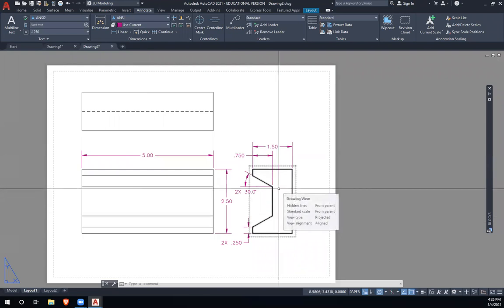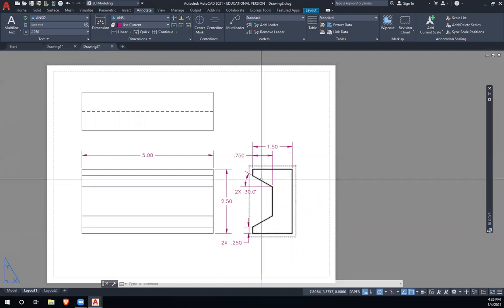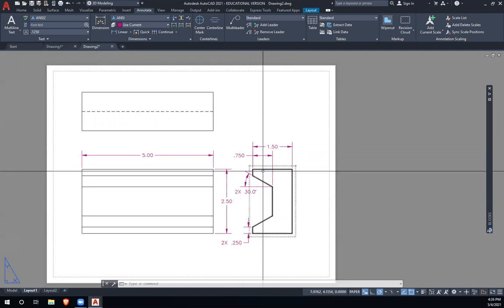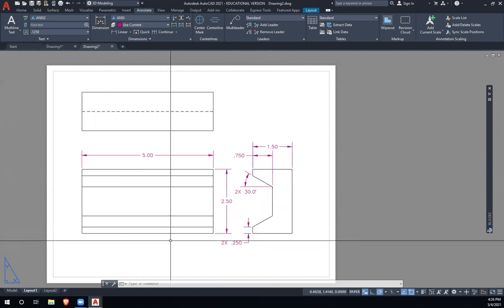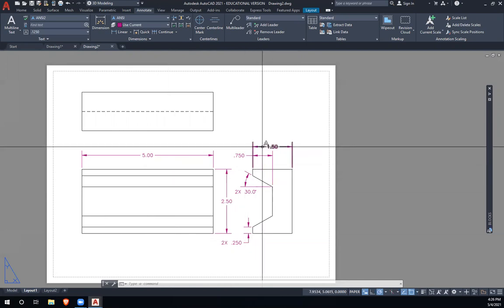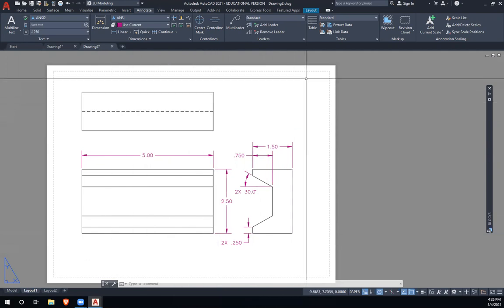That's actually the length of that edge, whereas this surface is not that shape of the surface anyway. Okay. Unless absolutely necessary, dimensions should not be placed within the outlines of the view, right? So just like what we said, we tried to keep all the dimensions off the part, right? So none of the dimensions are inside the outline of the part. That's good. And notice I didn't put that 1.5 inch dimension on that top view, even though it felt lonely out there not having a dimension on it.